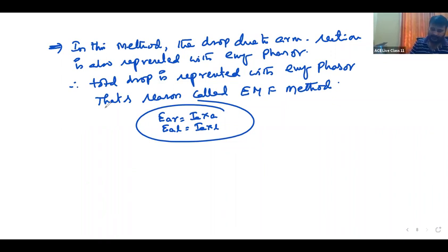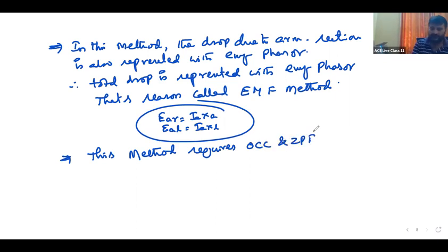See, this method requires OCC and ZPFC. No, OCC and SCC, not ZPFC. OCC and SCC.